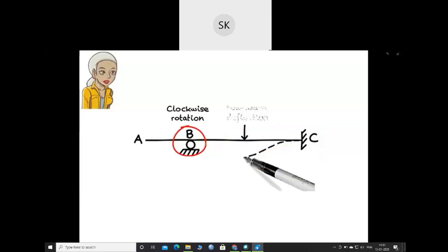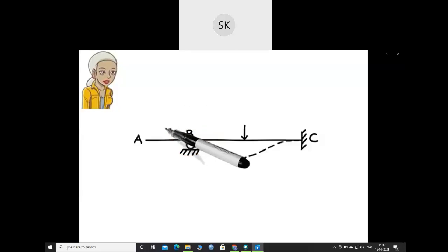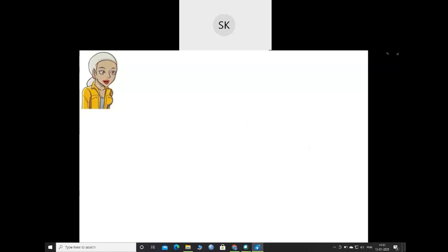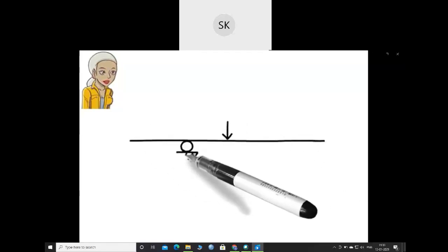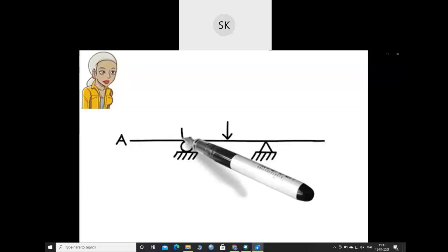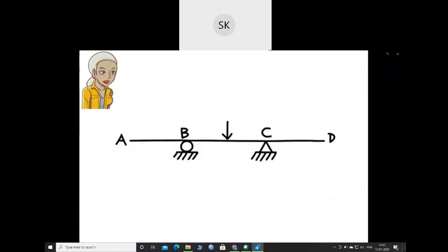The deflection starts decreasing past the point of maximum, going back to 0 at B, where the beam is forced to turn clockwise. Since there is no load pushing down on segment AB, the segment deflects upward following the direction established for the beam. Here are a few more examples illustrating the process of drawing the deflected shape of beams. Here, the beam deflects downward under the load in between the supports.